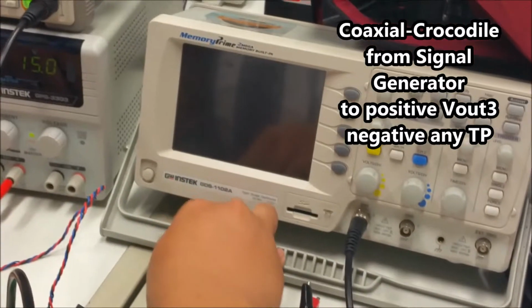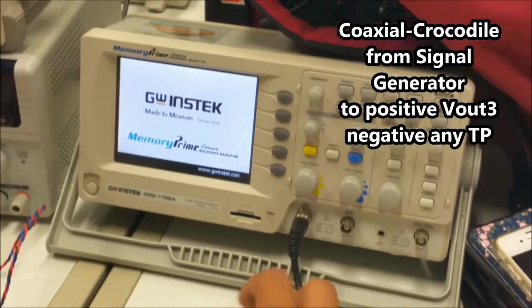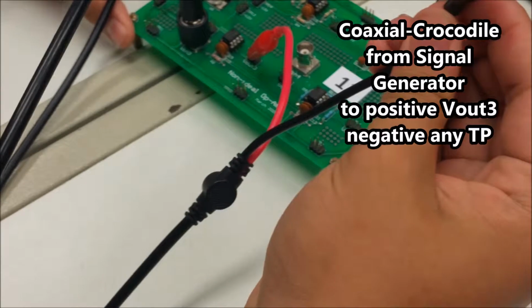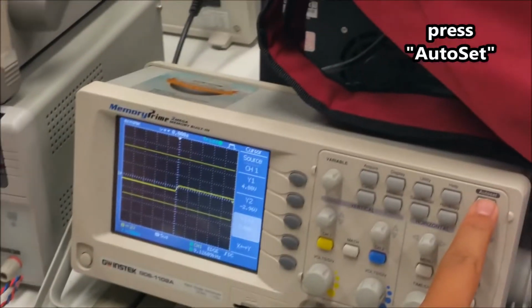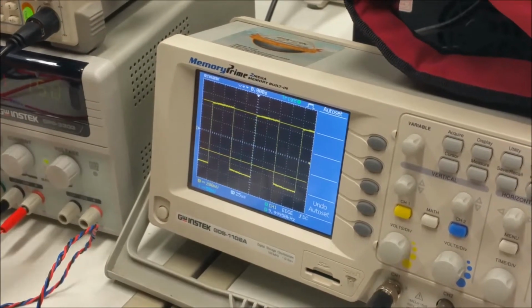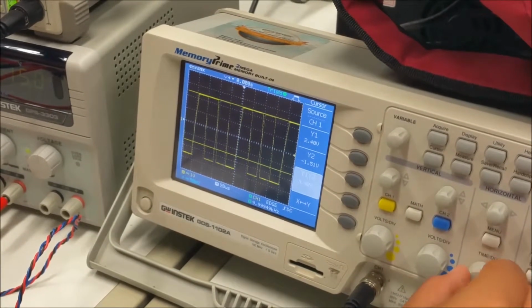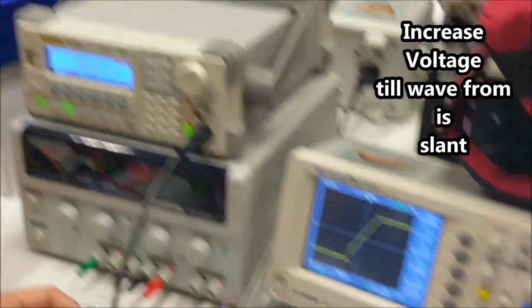Turn on the signal generator and connect the coaxial end from the signal generator to the positive end on Vout3 and the negative end to any TP surrounding of the crocodile cable. Now press on auto set and your waveform will appear. Now increase your voltage until you see a slant on your waveform.